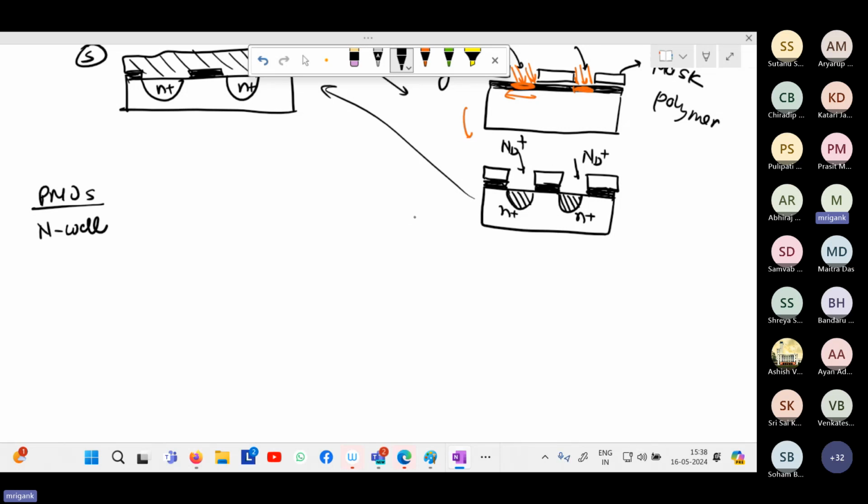Initially you have already doped the entire wafer. We started with doping it with P type. So for fabricating NMOS, you started with doping that entire wafer uniformly with P type impurities, P type atoms, so that you can fabricate your NMOS on the top of that P substrate. So we have created a P substrate. The whole wafer has been converted into a P substrate by doping it with acceptor impurities, and you have created your NMOSs.